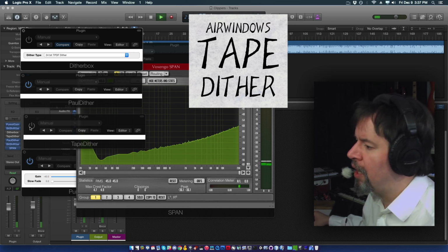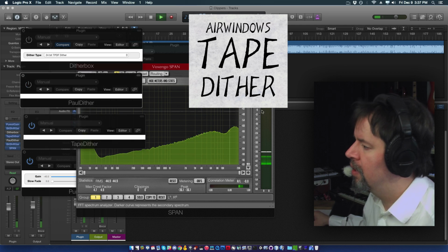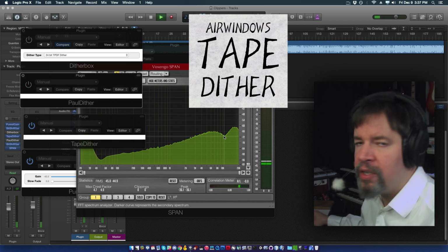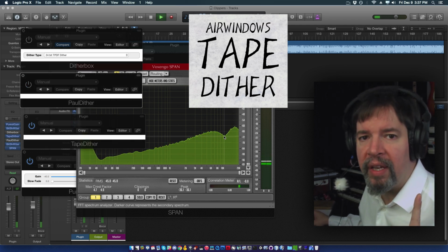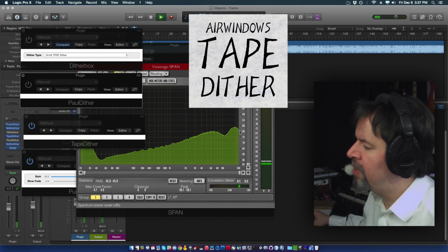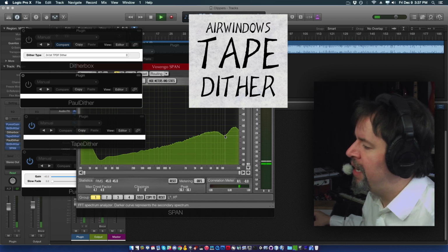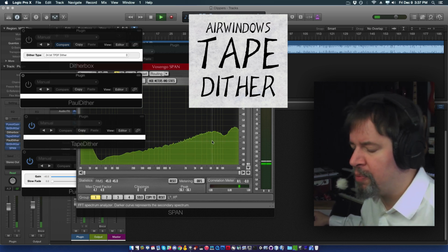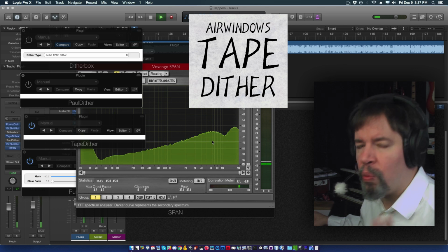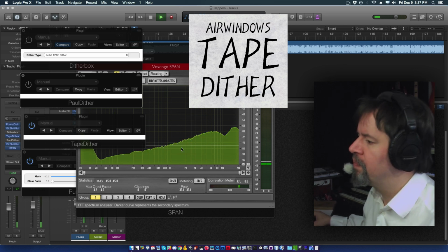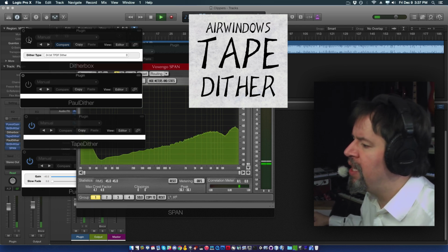So what I ended up settling on is 4 samples of delay. And 4 samples of delay gives you this. 2 samples also gives you this, but without the notch here. And then 8 samples gives you another notch around here or whatever, but it starts to become weird and overly colored.